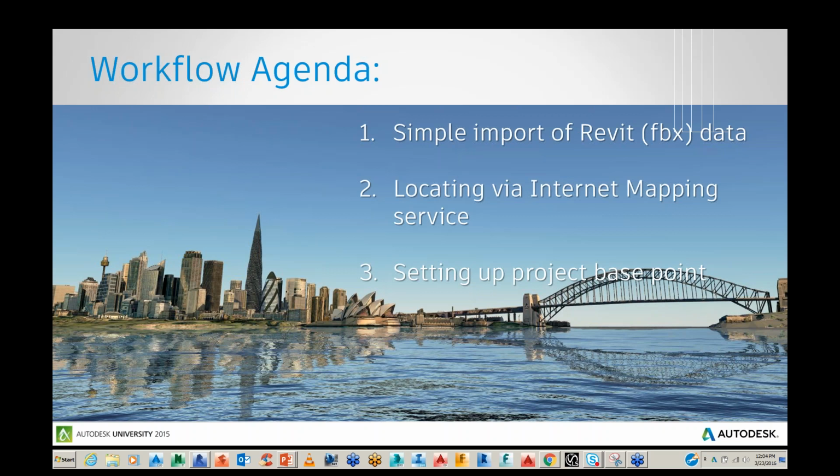And then finally, the more detailed setup, this is setting up your Revit model with a project base point. And for this presentation, it's going to be based on the map grid of Australia, Zone 56, because the building in question is going to be located in Sydney. And I'll do a bit of a deeper dive on that, how we can get information on the map grid of Australia, how we set it up in conjunction with other applications like Civil 3D and Infraworks 360 application.